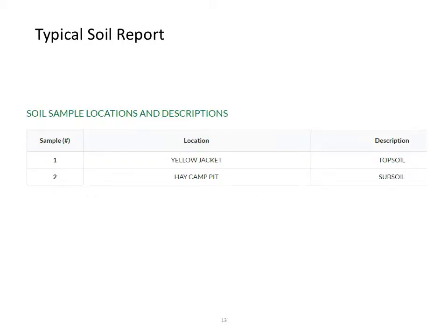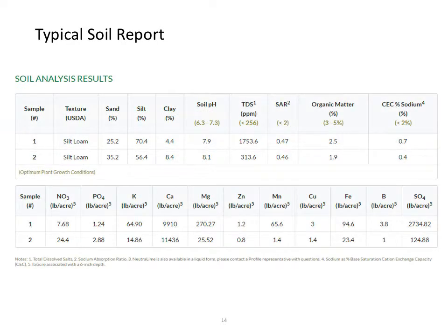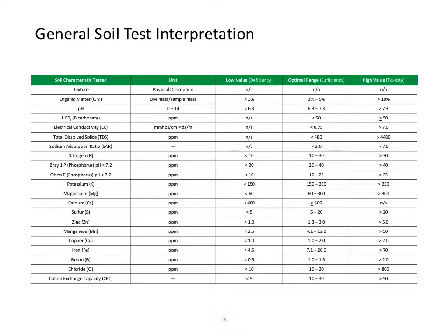And here's a sample soil report. This is actually the Dolores, Colorado area. So number 1 here is the topsoil. Number 2 is the fill dirt. Again, not going to go into each of these different parameters, but kind of the big 3. You're going to have organic matter, pH, and salinity. On this one, organic matter is actually pretty good. pH and salinity are a little high, but nothing we couldn't work with. So, and then tab 1 more.